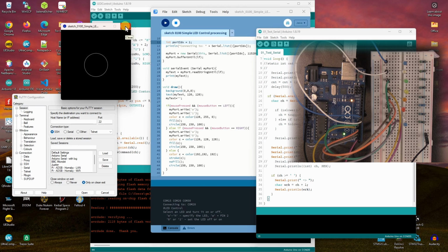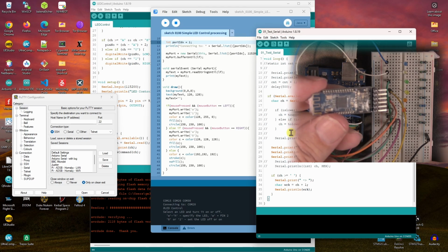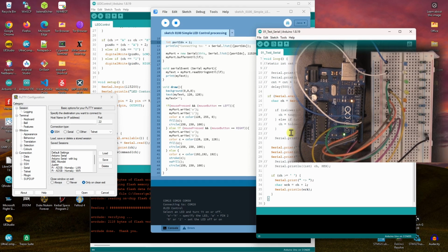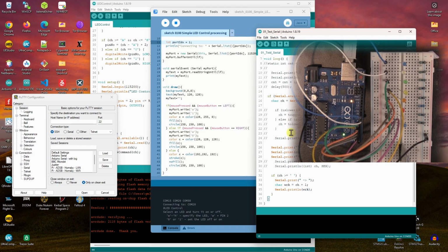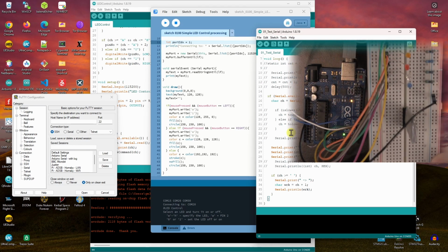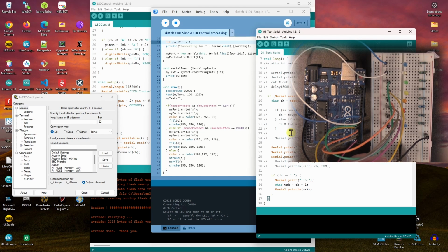Now I'll do one more little example, but first I need to get a little Bluetooth module. So this is a simple Bluetooth module. What I'm going to do is put it in here. It's off the camera, but I've bridged the power rails at this end of the breadboard, so I've got the ground and the +5 coming in there. In fact, I'll adopt my policy of turning the power off, and make sure I connect it up correctly.